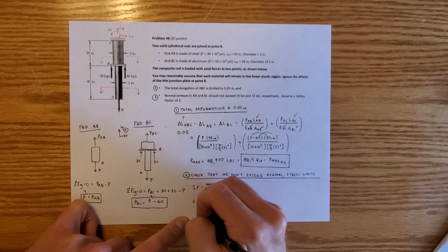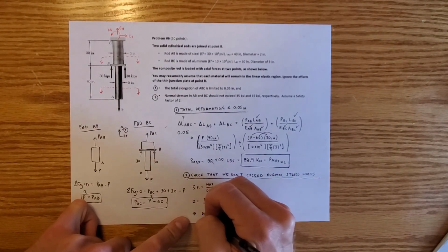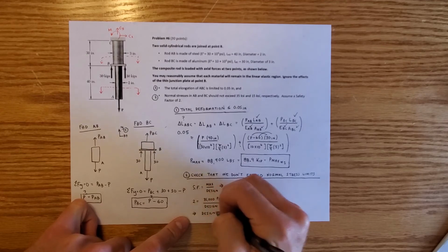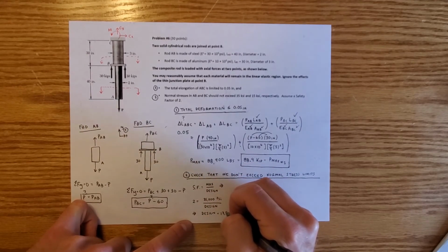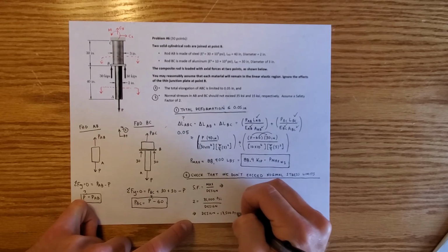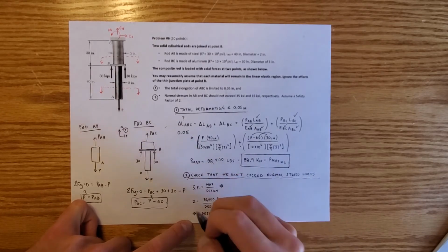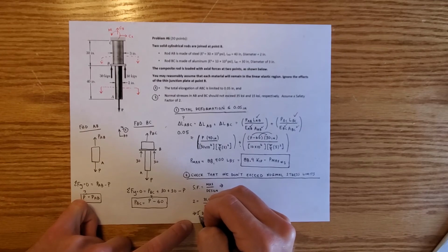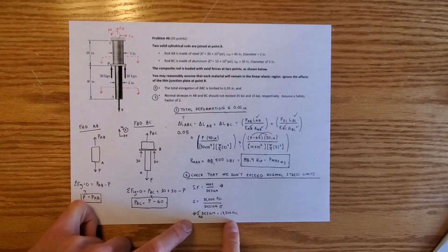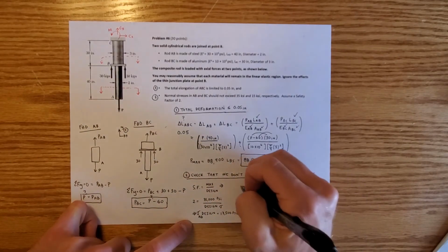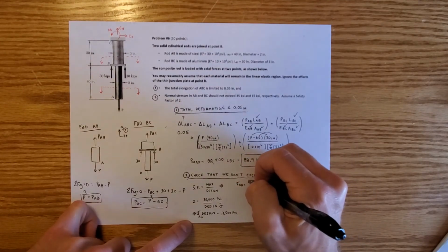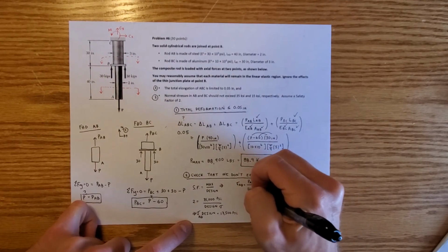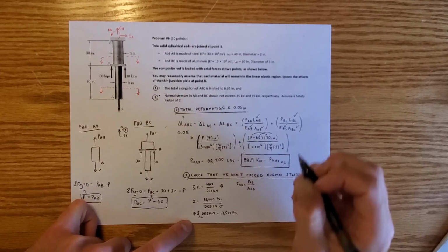So what this tells us is that the design we should use to calculate the P is going to be equal to 17,500 PSI. And this is the design sigma, or sigma design of AB. So if that's the case, we know that sigma AB is equal to PAB over the area of AB.